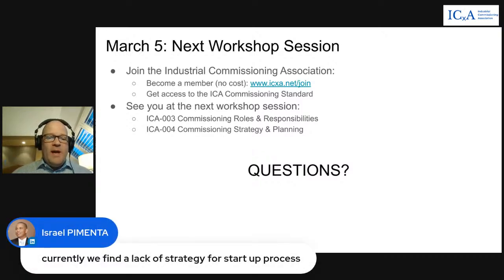Currently, we find a lack of strategy for startup process. Absolutely, and it's hard on projects, right? If you don't have an idea of how you're going to start up your projects, or what energization sequences you're going to follow, or what your introduction of process fluids are going to be like, then you're scrambling at the end of projects. And that needs to be defined during project concepts stages or project FEED stages.